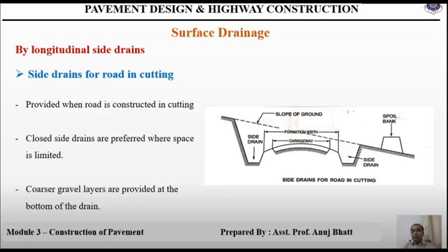Now, when a road is constructed in a cutting portion, the side drains are provided on either side of the road. The drain should not overflow in any circumstances. Closed drains are preferred, as open and deep side drains are dangerous where space is limited.